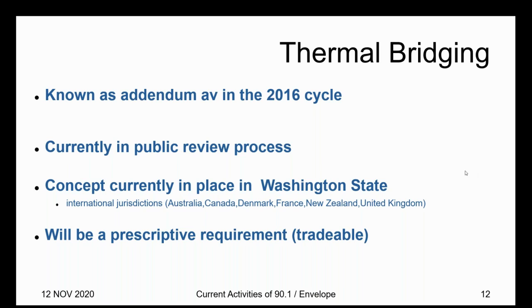And the concept is basically that when we think about buildings and we think about simple insulation strategies, we assume that everything meets perfectly. Your wall insulation perfectly meets your roof insulation. Your windows are perfectly aligned with your insulation. We sort of idealize all of these things. Now, we know in real life that that's not the way buildings are built. There's lots of things that poke through the insulation. There's junctions. There's different geometry. And so we looked at this and we tried to say, okay, we're going to start to quantify what this is in all these thermal bridges.